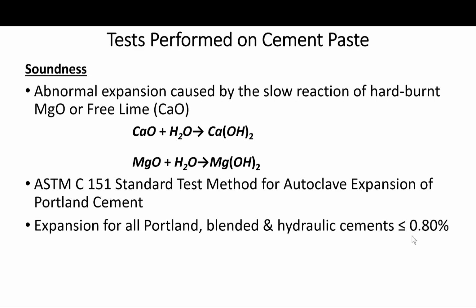One thing though I have to mention and to warn you about, these accelerated tests clearly do not simulate service condition. And the amount of expansion may be affected by a number of factors, such as the fineness of the cement, the C3A content, and others. So these tests can only serve as a guide and cannot provide absolute indication of a tendency toward unsoundness for a given cement. So this is just an indication.